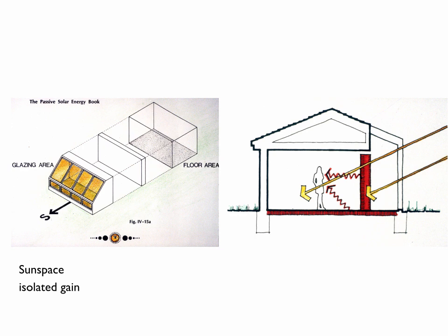So the idea here is that we're going to concentrate all of the area where the heat is collected into one space. Therefore, some of the other spaces in the building can be freed up and not have to have so much glazing area. We're also going to maximize the amount of thermal storage that we have in that space. So instead of just maybe one surface being massive, we're going to have as many surfaces as possible be massive so that we can make sure to store and capture all that heat that's coming through the glazing.